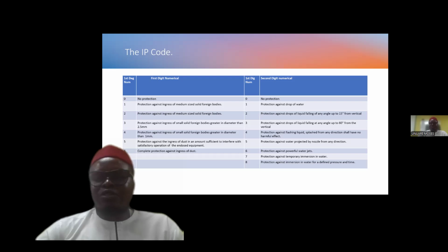with explosive protection. Let's take, for instance, a flameproof enclosure, which is noted as Ex d, often requiring a high IP rating to prevent ingress that could compromise the flame path.